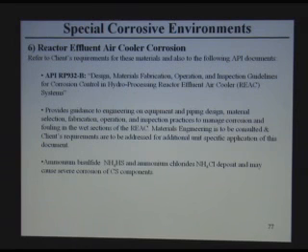But for us, we look at the hydrogen sulfide partial pressure and ammonia partial pressure, and multiply the mole fractions. We get some factor, they call it the Kp factor, which gives us some guide. Where are we? Can we use carbon steel, or do we have to use some alloy? So it is challenging. The piping design is also very critical to ensure that the flow is equally distributed among air cooler banks and eventually in each tube.